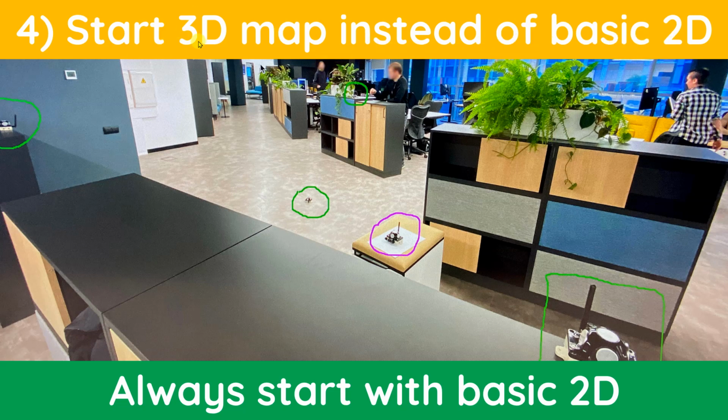instead of complex 3D, basic 2D would be built. For example, what is basic 2D? Our recommendation is very simple. Put the stationary beacons on the wall, high on the wall. Why? In this case, it's more difficult to make a mistake with non-line of sight. So this beacon and this beacon, for example, could be put on some wall, and then okay, fine. Then line of sight is almost automatically provided because it's difficult to make a mistake,